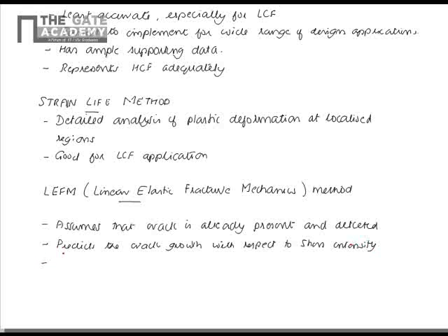And this is most practical for large structure applications. So these are basically the three methods which are used for predicting the fatigue life: the stress life approach, strain life method, and linear elastic fracture mechanics method.